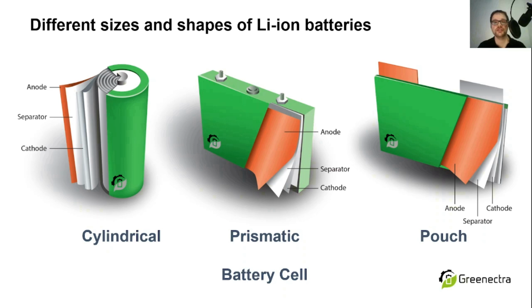However, energy density is a term that should not be only considered on the battery cell level. When we have a system out of many battery cells, the energy density on module level or pack level is much more important than on cell level. Imagine you put a lot of cylindrical battery cells together. You will always have some space in between them, but on module level, this space could be used for some cooling solutions.